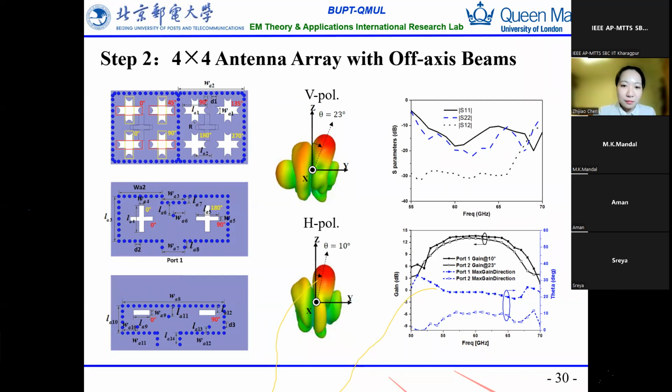So you can think of in terms of the conductor loss and dielectric loss. The moment you have higher electric field intensity, you face higher dielectric loss. The moment you have more surface tangential magnetic field, so n cross H, then surface current will be high. So think in that way. So obviously it will have higher loss, but not like microstrip line. Still, she is showing some improvement.